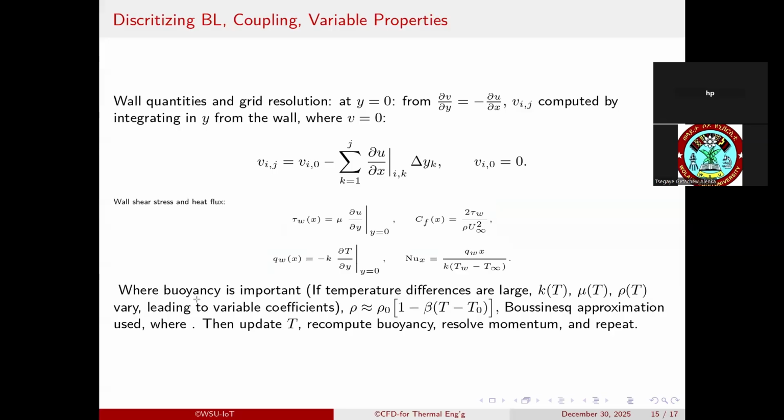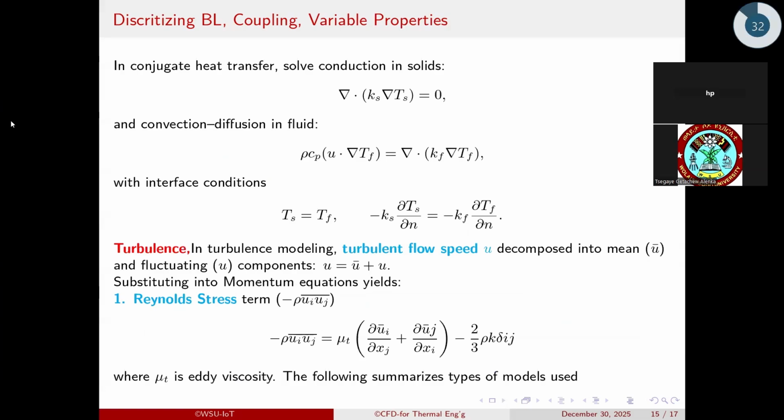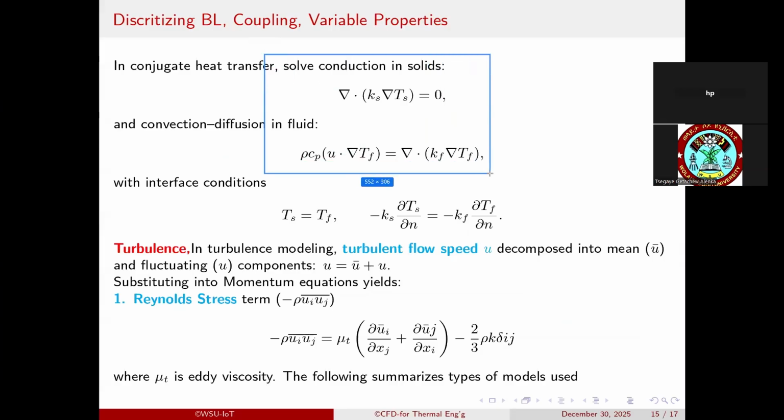Solve the energy equation for temperature profile determination. Analysis involving temperature dependent density using the Boussinesq approximation can be used to update temperature, buoyancy, and momentum. The equations are repeated until convergence. Heat transfer through the side wall is determined using conjugate heat transfer on all boundaries. The interface energy is determined using Gaussian diffusion.